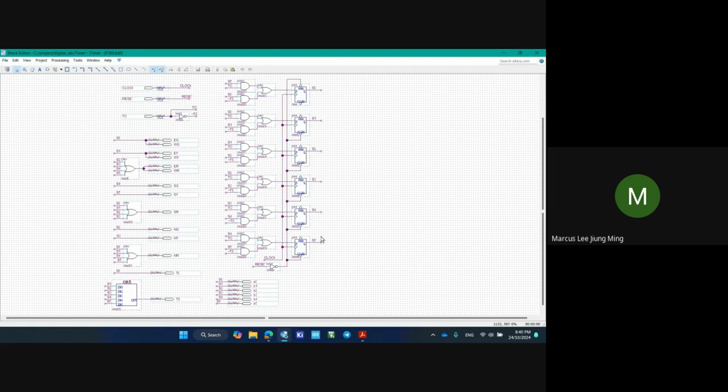Based on the zebra crossing system control module and state diagram provided, we can determine that there are 3 inputs and 14 outputs. We have added extra outputs S0 to S5, as shown in the schematic above, so that we can determine the changes between the states. The blocks placed on the left-hand side of the D flip-flops are connected to the input and are derived from the one-hot equation. Also, we use OR gates to connect to the output blocks because an OR gate allows the output to turn on if any one of the corresponding states is active.